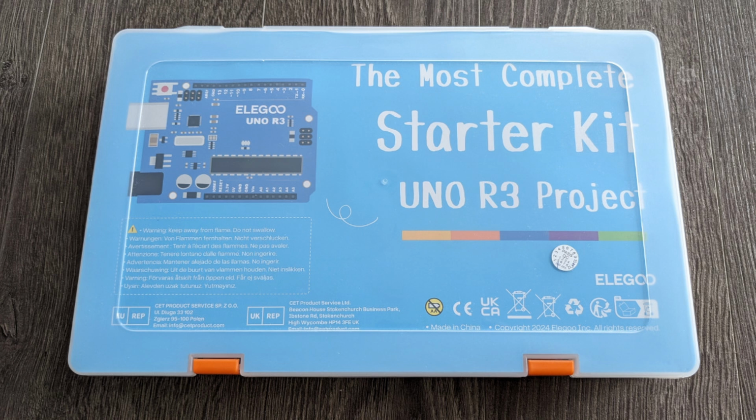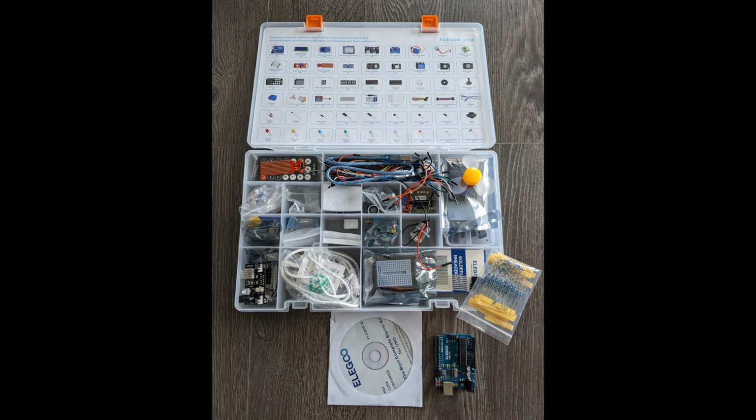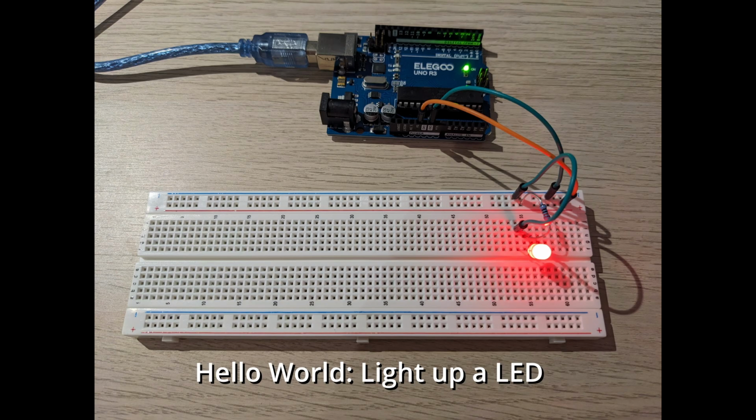6 months ago, I got myself this Arduino kit and went through all of its main tutorials and dug into the numerous questions that popped up along the way. And the first thing I did was to light up a LED. A simple exercise, but already exposes why a resistor is needed and why polarity is important for these diodes.